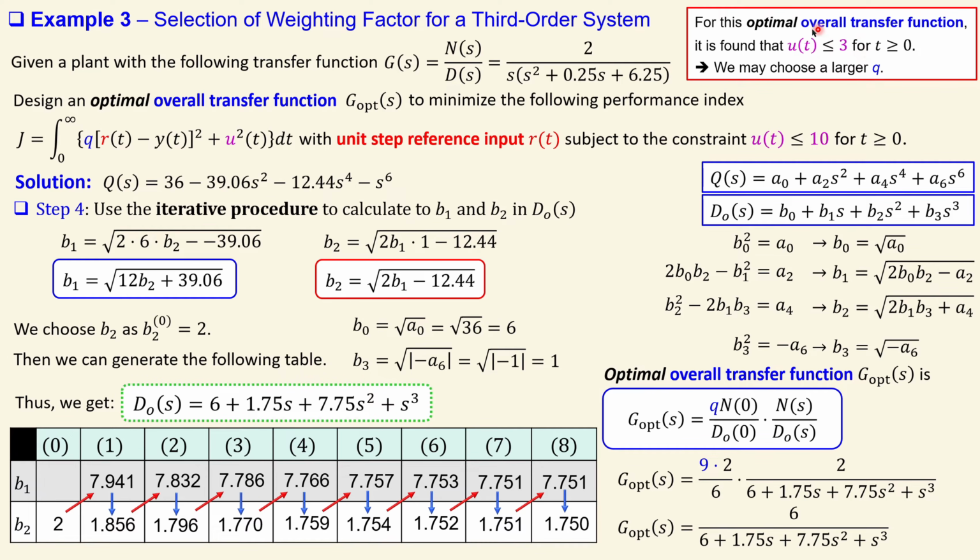You might ask, how do I determine that U was smaller or equal to 3? What you can do is look at the closed loop transfer function of the system, and then do the inverse Laplace transform in MATLAB, or you do the step response and you see directly the transient and how large that is responding.